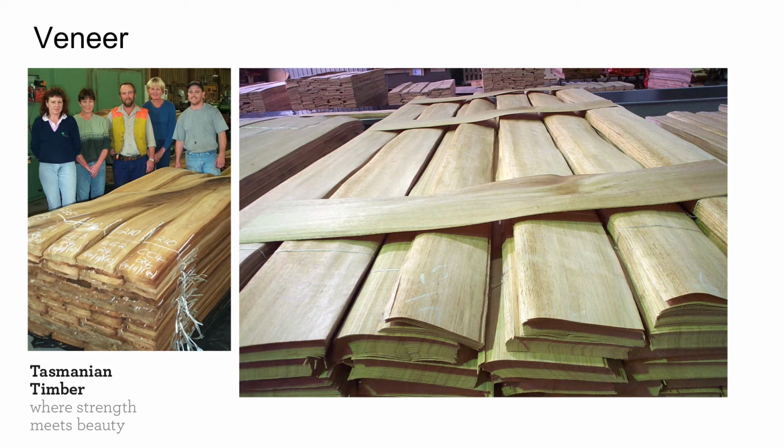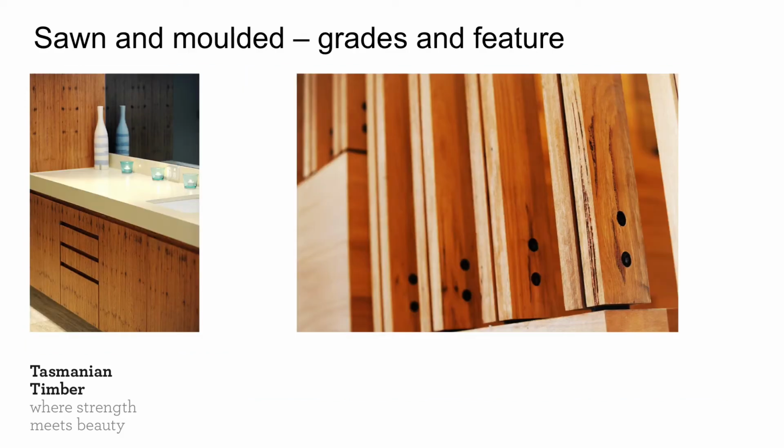So these are what's called bundles of veneer. When a veneer is sliced, each slice is kept in the order it comes off, so that you can colour match and book match the veneers to make an even looking panel. So you don't randomise them around much. Well, you can, but that's a deliberate process. But you then keep it bundled and then you grade the bundles.